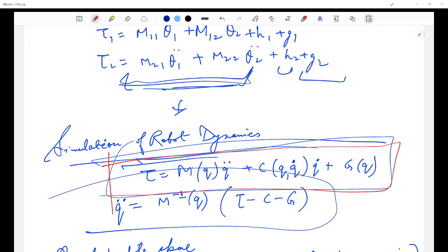Let's say your arm is folded, it is easier to rotate the arm and you see that it requires less effort. But if your arm is fully stretched and you're going to do the same motion, it is a bit harder. So your joint configuration actually plays a major role. Your inertia matrix depends on the joint configuration, and it makes the task either easy or difficult.